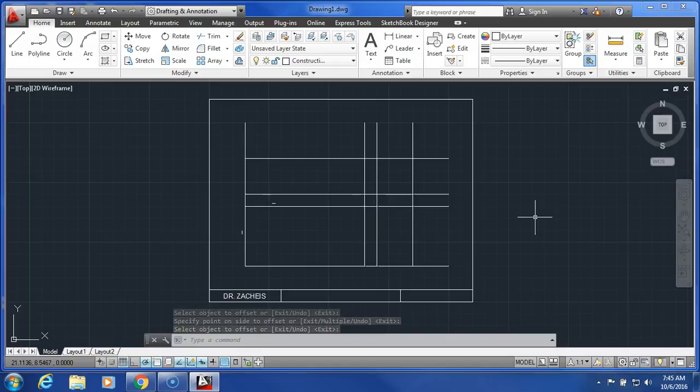Now all of your drawings will start this way. Again, I'm going to go over it again quickly. We went over 5 inches. We went up 2.5. Okay, that's the space of all the side views you'll do. Then we spaced a 1/2 inch between the drawings, so here and here. So this area right here that I'm running the cursor through right now, that's a space. Okay, that helped us space the front view, which is right here. Again, we went over 1.5.